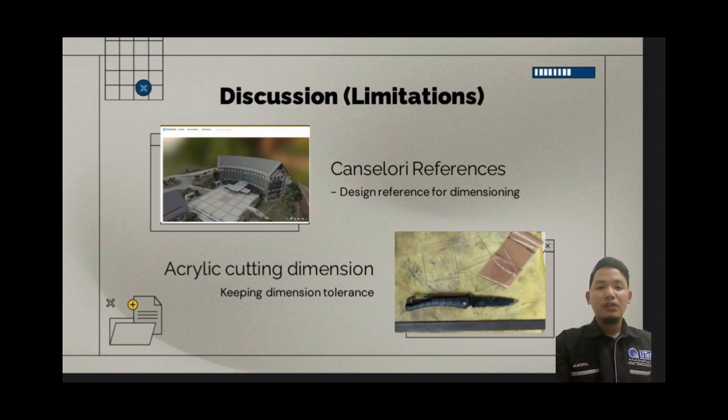Another limitation that occurred during our project is the acrylic cutting dimension. The acrylic had a big tolerance after cutting. So to make it more precise, we used a heated knife to cut it more precisely and more fluently.